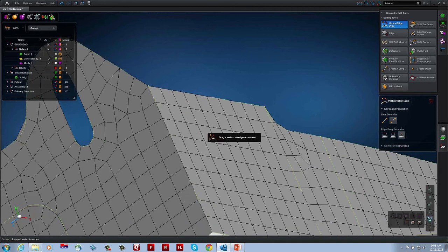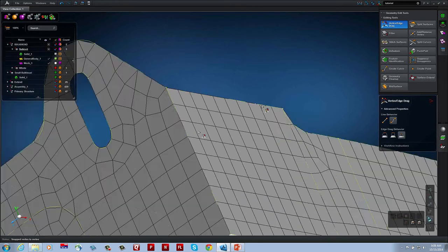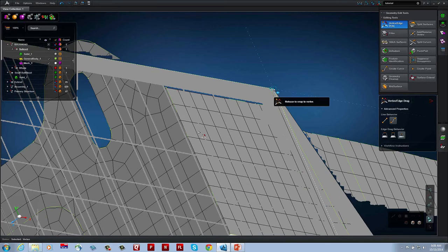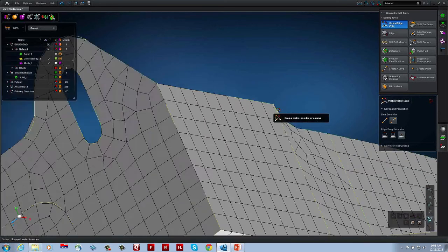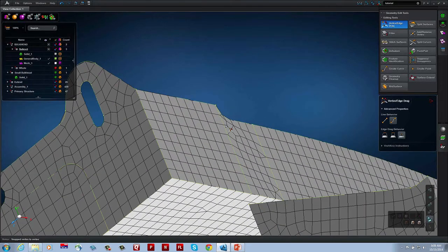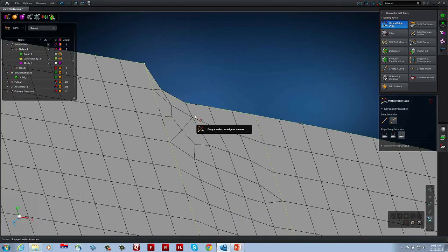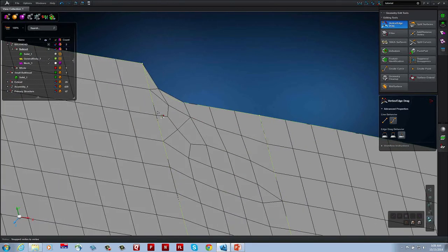Notice how the mesh is automatically updating every time I make a change to the geometry. I'm not having to do any remeshing. That's happening automatically. Now, here's an interesting area. I have a poor mesh in this area right now. Let's look at fixing that.